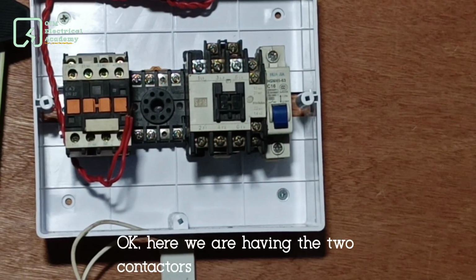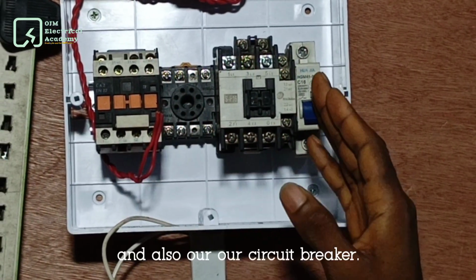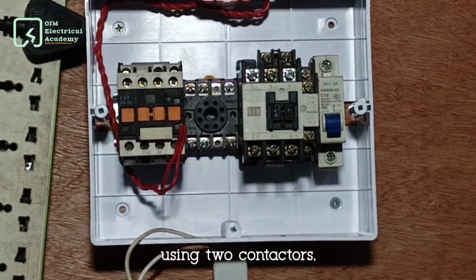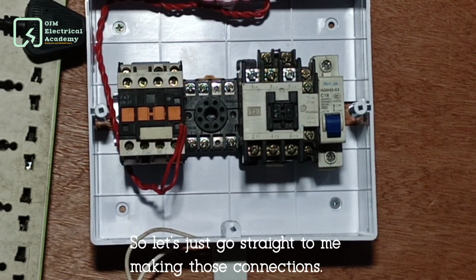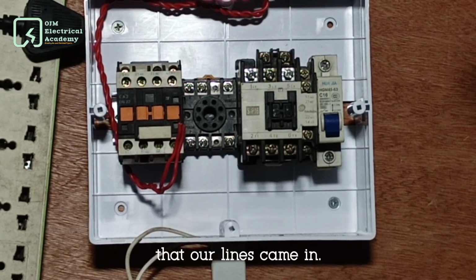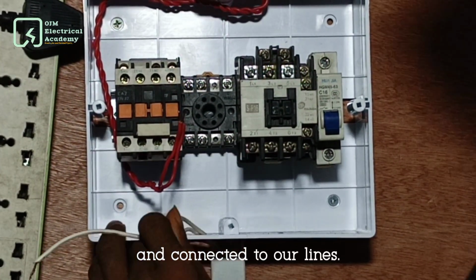Okay, here we have the two contactors that we stated initially, with our relay base and also our circuit breaker. What we want to achieve is to build an automatic changeover using two contactors. So let's go straight to making those connections. If you look at our diagram, you will see very well that our utility supply came in and connected to our lines.